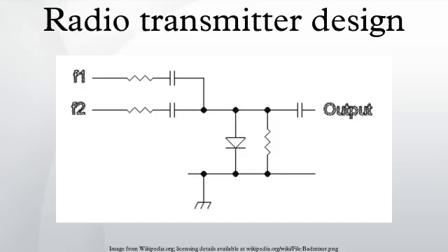Connecting the 90-degree delayed signal from either the audio or the carrier to the other mixer will reverse the sideband, so either USB or LSB is available with a simple DPDT switch.